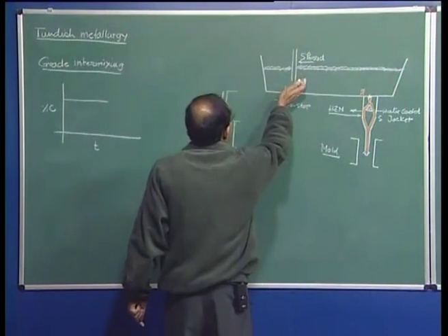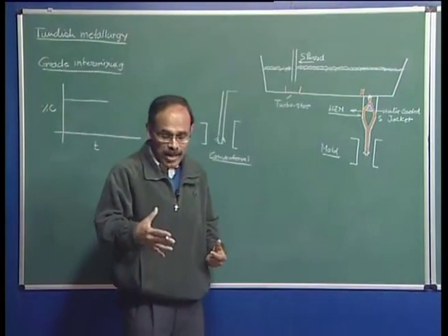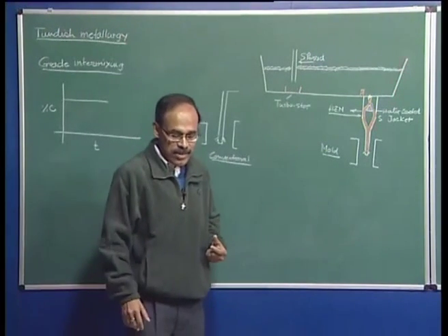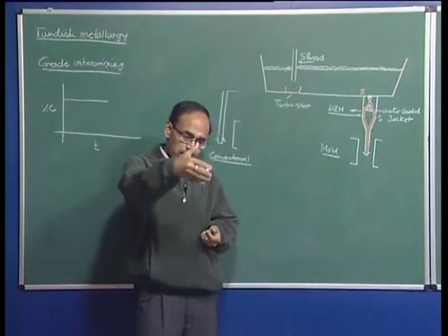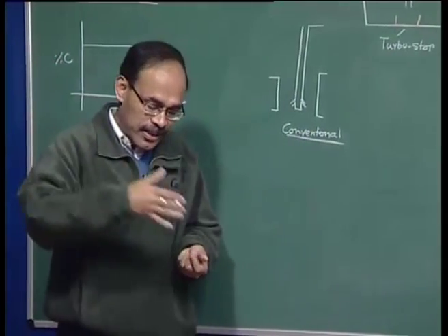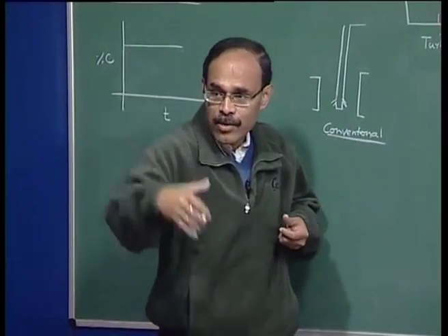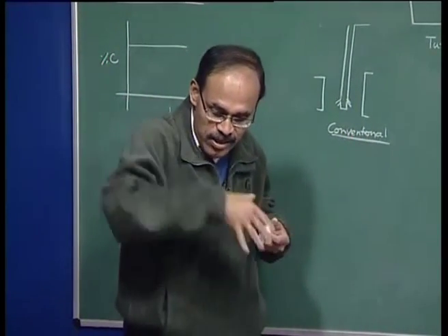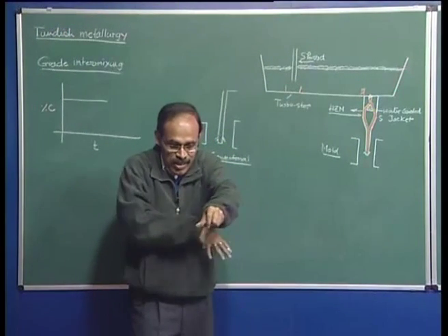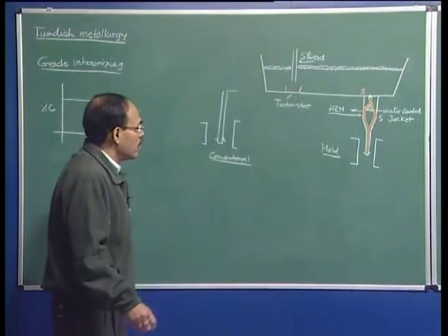Now, as soon as I remove this ladle, for example, and bring in another, what does the turret look like? The turret looks like one ladle is there from which molten metal goes down into the tundish. Another ladle is behind that ladle, at an angle of 180 degrees, or diametrically opposite. So, suppose you are looking in this direction. The ladle at the front is exhausted, the turret undergoes rotation and this ladle is brought in, and material from this particular ladle now starts to go into the tundish.